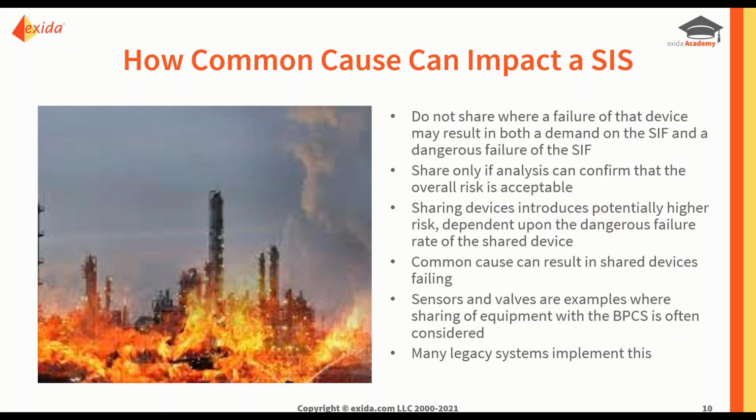So how does it impact? Well, we should not be sharing where a failure of that device could result in both a demand on the SIF and a dangerous failure of the SIF. So again, the standard is clear about how we qualify independent layers of protection, and it's that key word, independent.